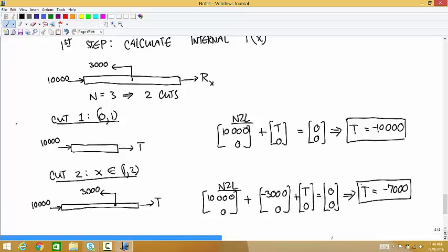Okay, so the second half, is that tension or compression? Compression. So the second half is also going to shorten, and so the whole thing is going to shorten. And we're going to figure out how much by just calculating the shortening in the first half, calculate the shortening in the second half, and just add those two results together.